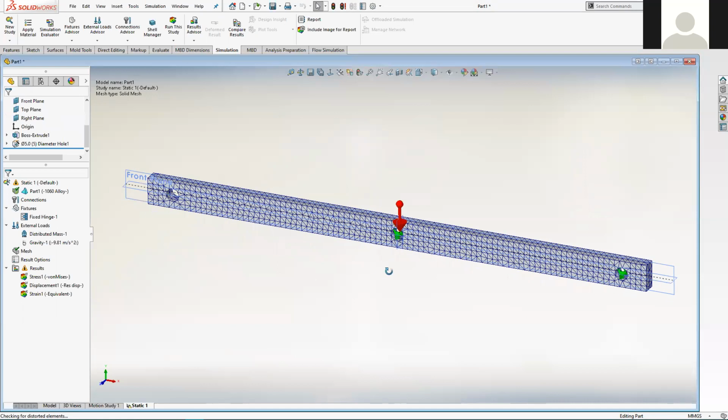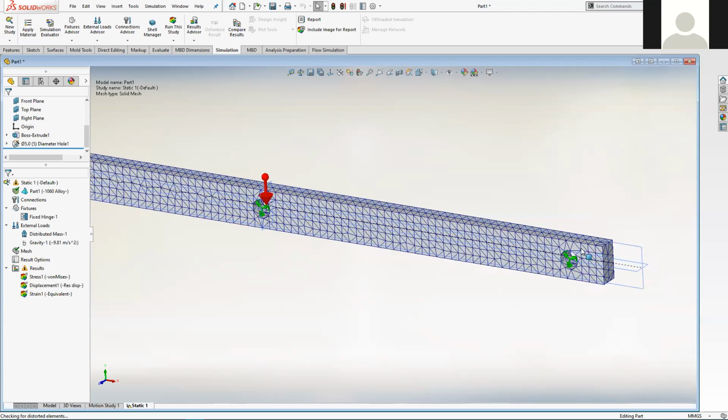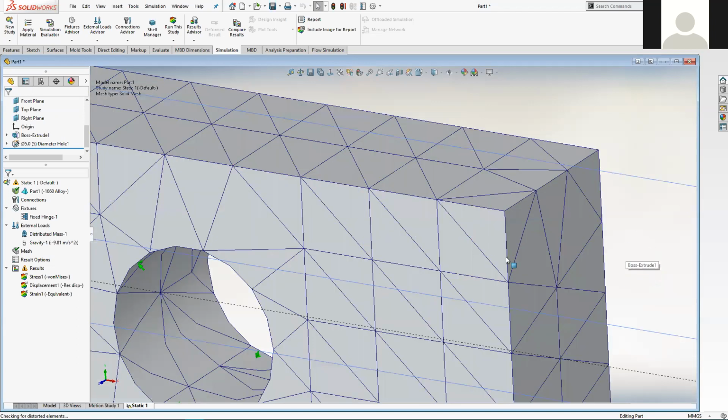And this is the finite element bit of finite element analysis. It chops that solid shape that we had before into a finite number of elements. And that's what these are. They're little triangular-sided 3D shapes. And what the system does is at these node points where the triangles meet each other, it runs the force and stress calculations that it needs to run.